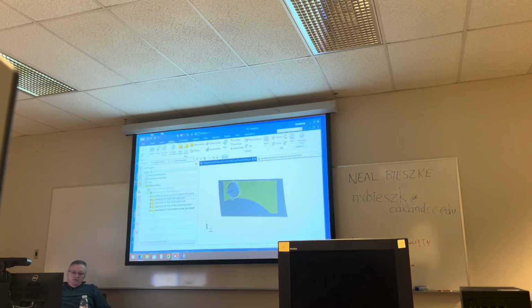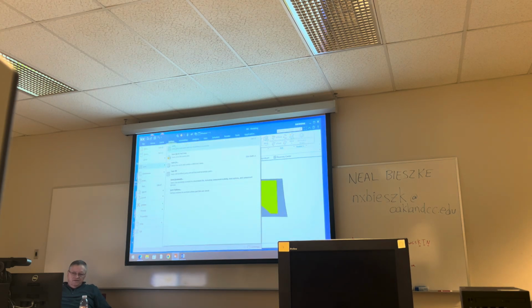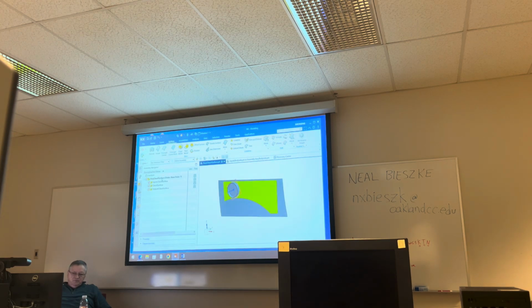We did this, we basically fixed this as the Class A person, okay? And I am gonna save the whole Class A assembly. The fast way to save that, just in case I made changes in all these, I know I said this before too, if you make the top of the tree the work part, and you hit this, or File, Save, they both say the same thing, it saves the work part and any modified components. That's the work part, and the component, any children. So this will save everything that needs to be saved, starting here, alright? So I did that. So now my work as the Class A person is kinda done.